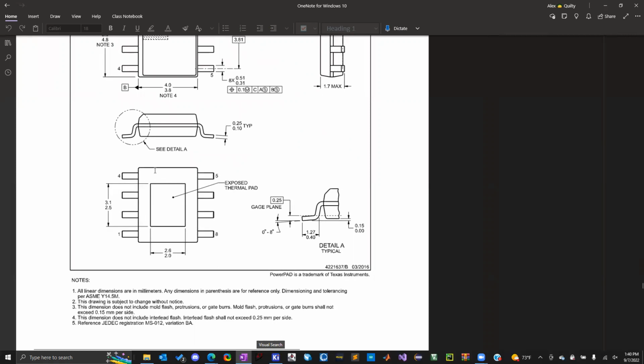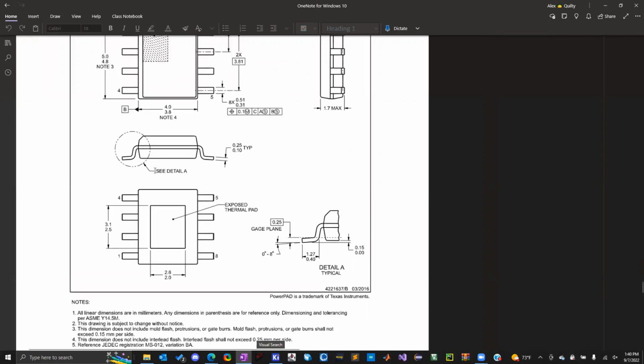So ideally, you would find the component. If you didn't have the footprint, you would Google it and see if somebody's already made the footprint, download it, import it to KiCad, and then repeat that for all your components. For integrated circuits or chips, they usually have that general package. For resistors and capacitors, you'll have to find them yourself.